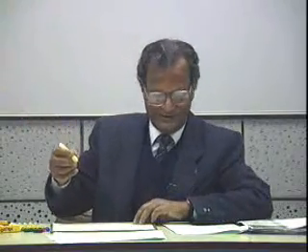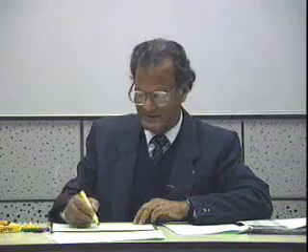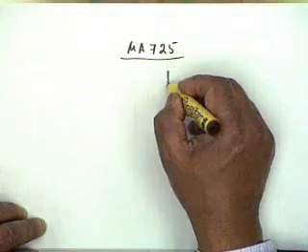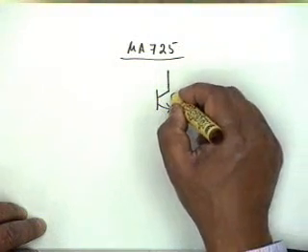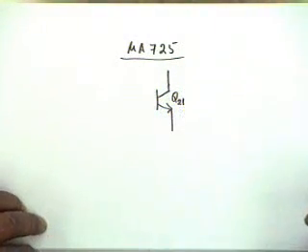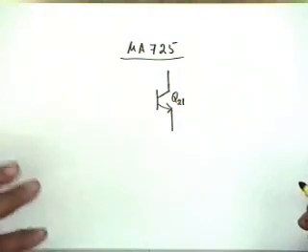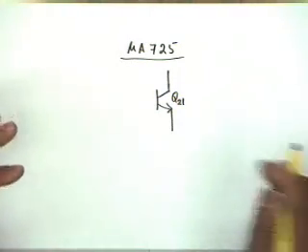The actual circuit is this. You will see that the numbers of the transistors are very large numbers. I mean, these are parts of the total circuit. So I am drawing only the output stage. Output stage is required to drive some current through a load, and therefore it is a power amplifier stage. It is a class AB stage, so that there is no distortion.